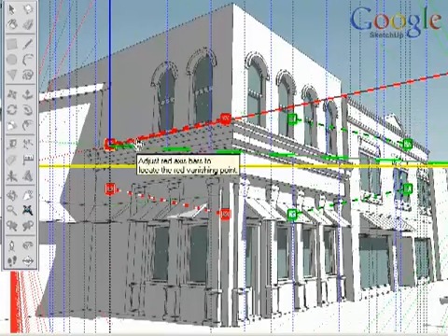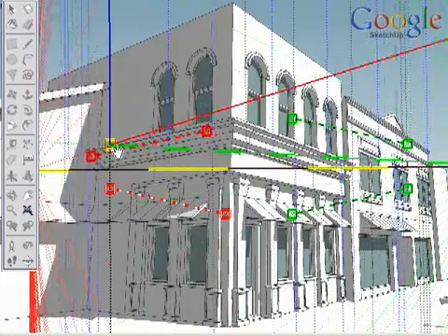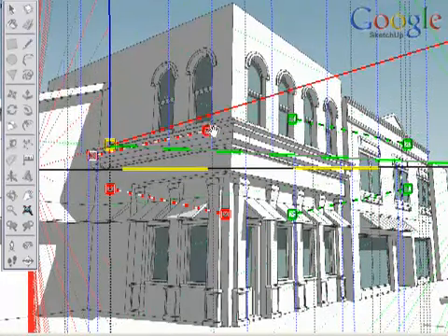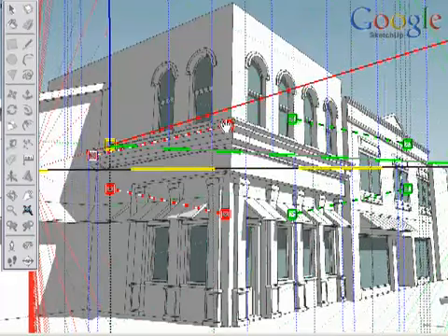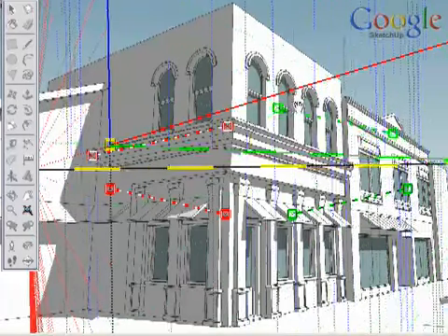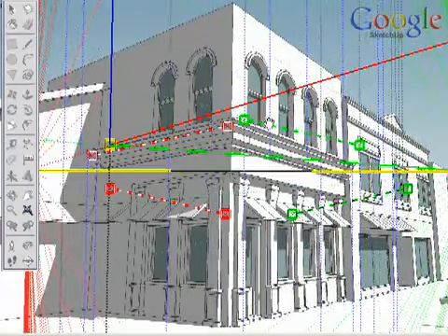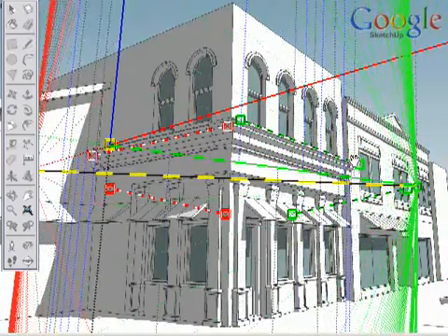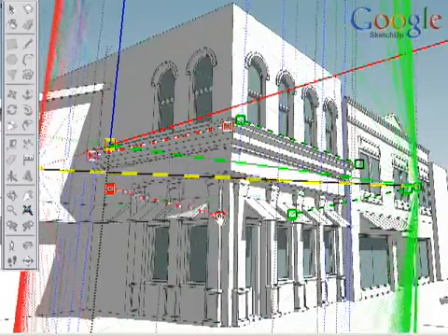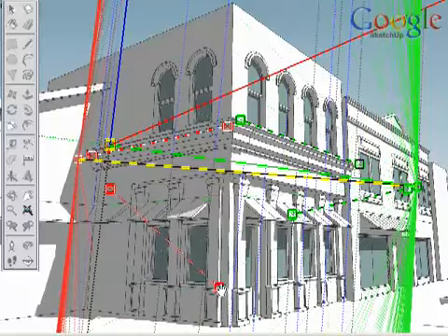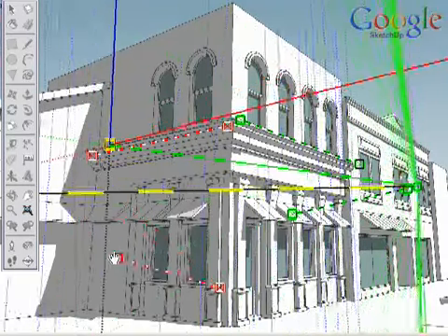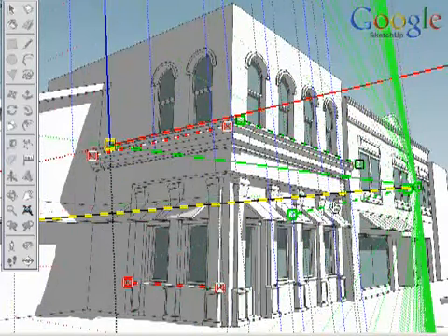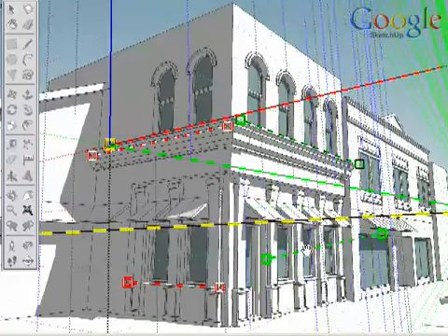The image is placed as a background image in SketchUp, and a grid of red, green, and blue lines is displayed. You can see by grabbing and dragging around on the red and green axis bars, you affect the overall grid, which is really affecting the perspective. Now use the axis bars to align the grid to your photo. Click and drag on the bar itself or on the bar grips.